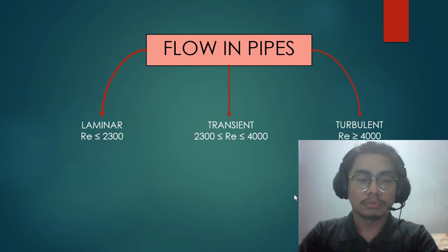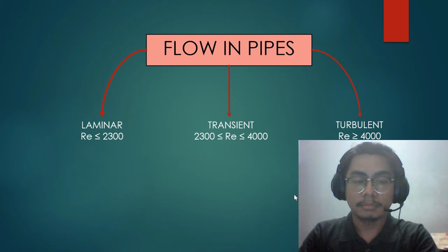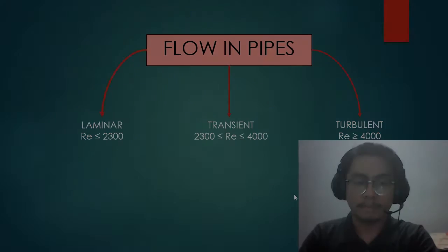The laminar flow was visualized as smooth, streamlined, and highly ordered. The flow is laminar when Reynolds number is below 2300, and it is fully developed if the pipe is long enough that entrance effects could be ignored. Each fluid particle in fully developed laminar flow moves at a constant axial velocity along the streamline, and the velocity profile remains the same in the flow.